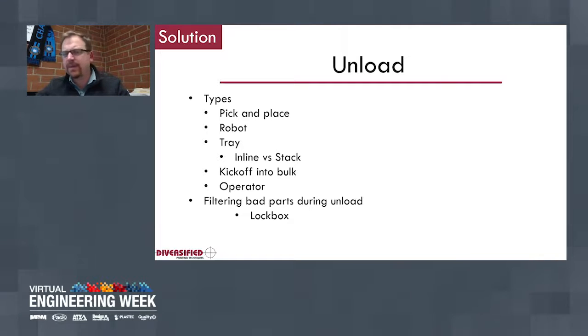And that's important to think about too, is we put on an automatic shutdown. If we pass so many bad parts within an hour or within so many cycles, then the machine will go into a shutdown mode so someone can figure out how to fix that.